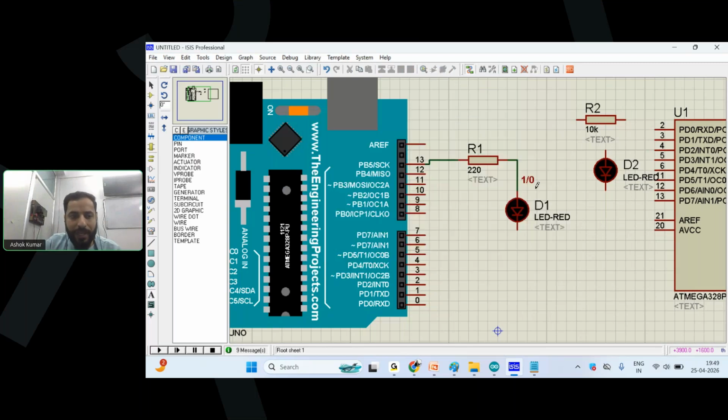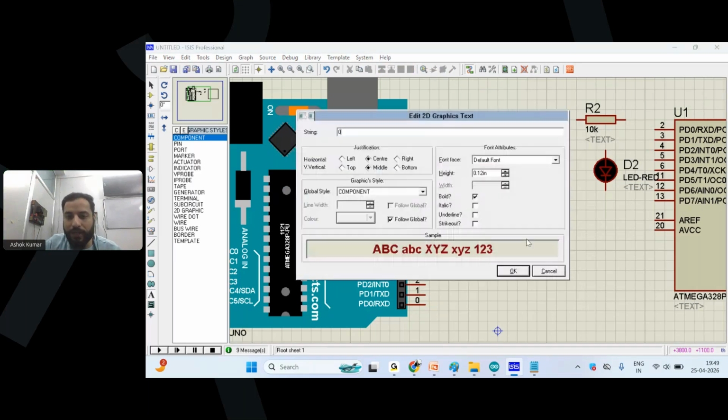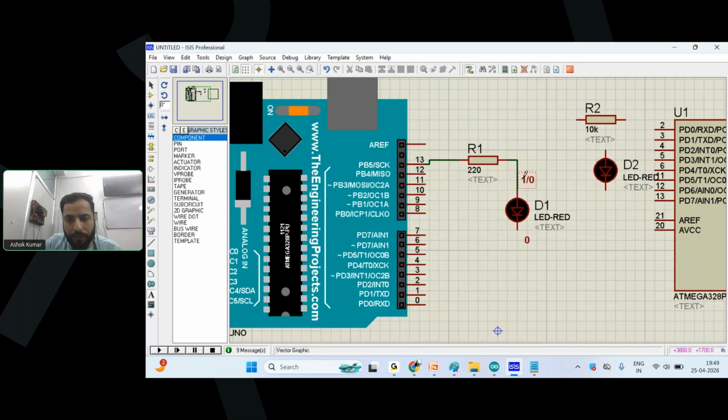So on the other side, if I connect the ground, which means I connect logic 0 permanently, then when I send 1 on the positive terminal, the negative is already 0. So the potential difference is 5 volts: 5 volts minus 0 volts is 5 volts, right? And when I send 0, 0 minus 0 is 0 volts. So when it's 1 and 0, there is a potential difference and the LED goes on. When there is 0 and 0, there is no potential difference and the LED goes off, right? So I need to connect a permanent 0 here, and the permanent 0 solution is always ground.